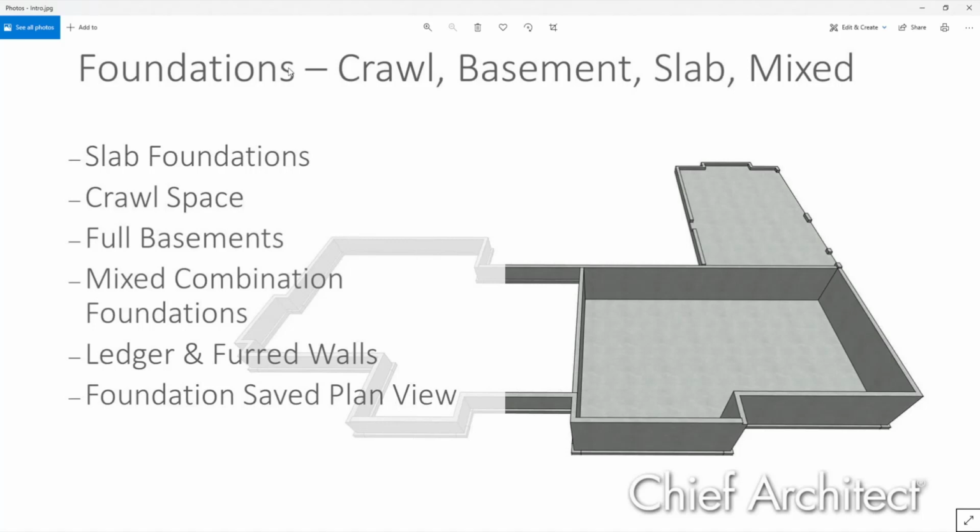Yeah, I think that, first of all, there's not an automatic way for the garage floor to slope in the program. You can take an elevation view and draw a slope line or put a pitch indicator on your floor plan view. And if you want to see it actually in 3D, I think the easiest way would just be to use your polyline solid tool in an elevation and a 1/4-inch slope, whatever you're doing in there.